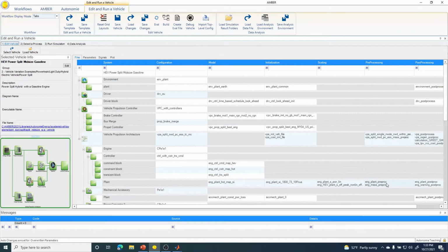You might also be given something like a BSFC map, brake-specific fuel consumption, and you'd want to convert that into an efficiency map to do scaling. There's also cases with plotting where you want to have the map not as fuel rate as a function of torque and speed, but as a function of power and speed. So a pre-processing file would do that type of computation.